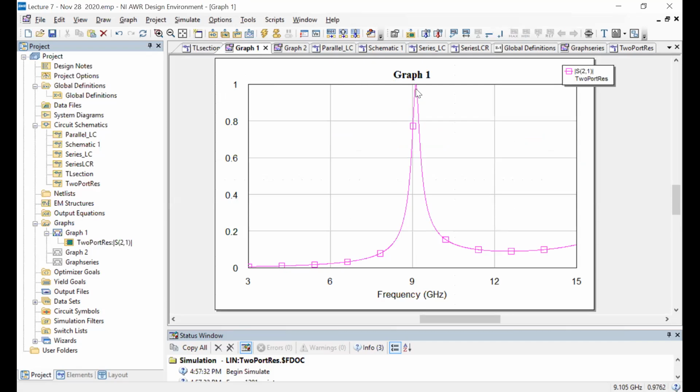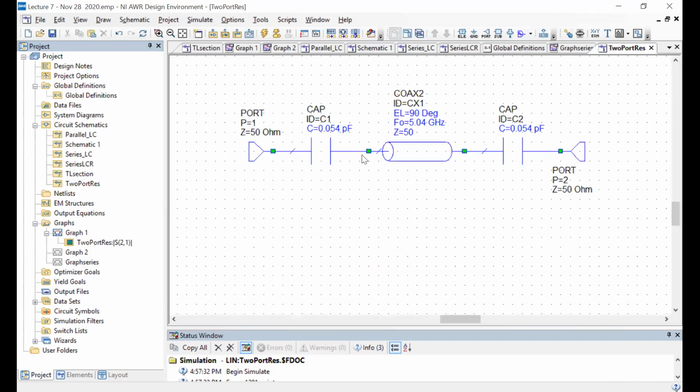That's why this is starting to look, you know, before we started this course and before maybe your exposure to reflection measurements, when we typically talk about a resonance, it looks something like this, or it looks like the inverted version where there's a nice dip in the middle, which we had seen, of course, in the reflection measurements with losses. Okay, so a lambda by 2 resonator of this type in transmission has a peak in the transmission on resonance.